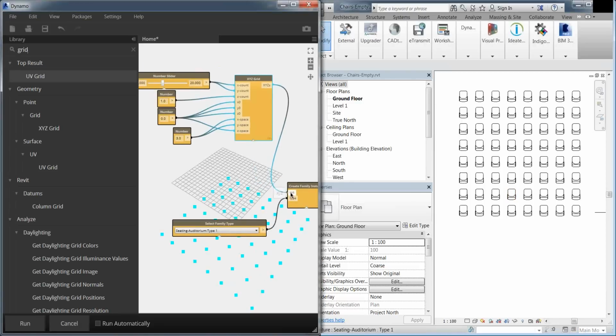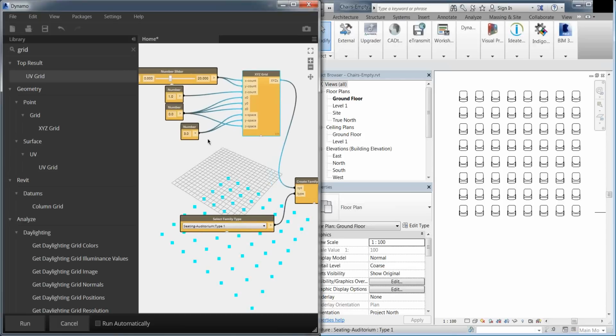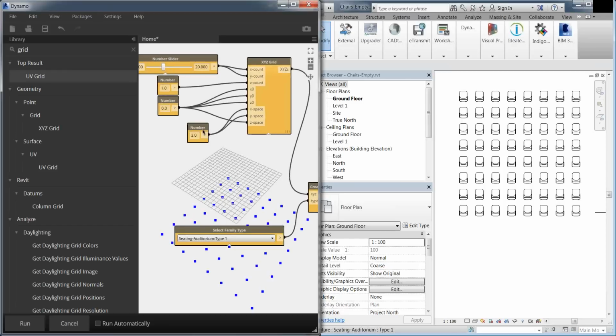So we're feeding in a list of points, not just a singular point, into the module here. You'll notice the XYZ space here, I've put in a 3. That's a bit of a bug with the older version of Dynamo. The older version works in feet, so we generally, here in Australia, work in metric and millimeters. If you were wondering, the conversion from feet to millimeters is to divide by 304.8. I happen to know that off by heart after doing it a few times.